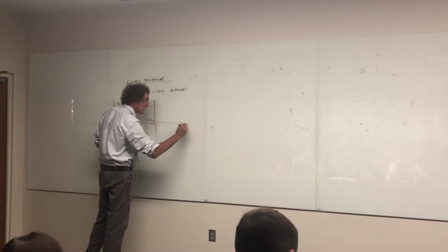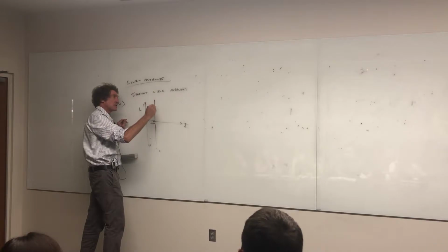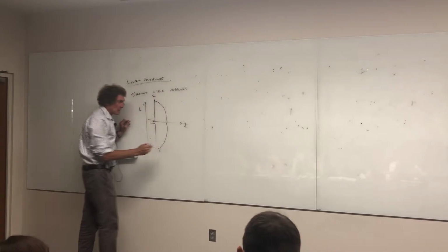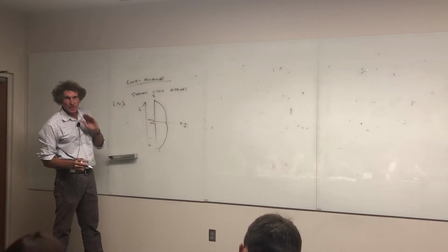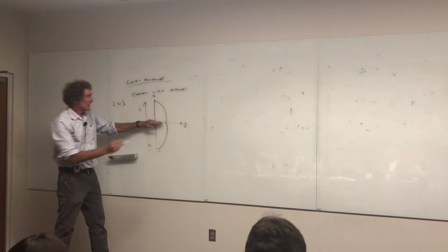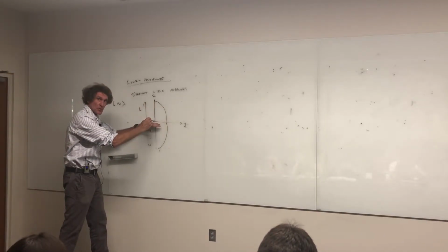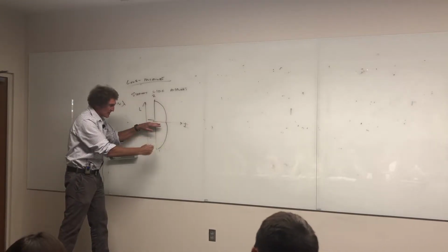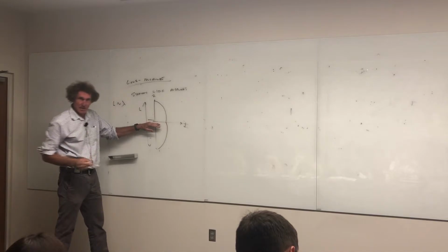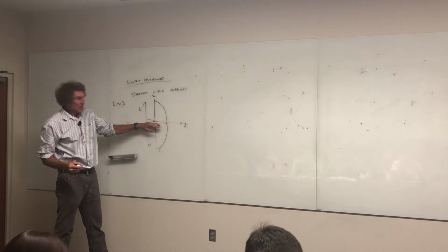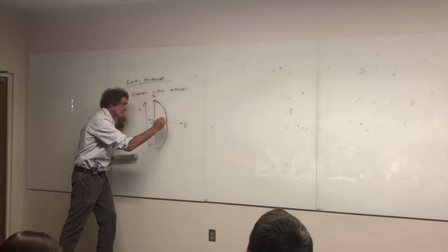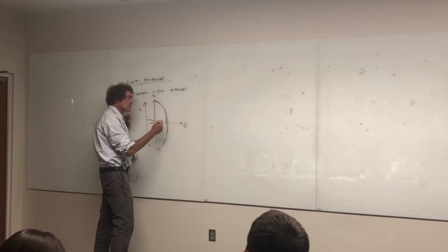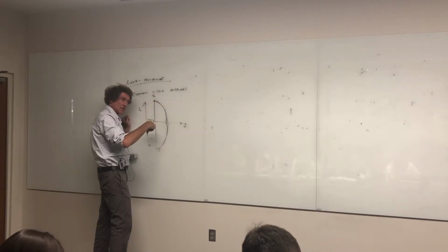And if we were to profile the current versus height, this is the z-axis, this is what you'll get. Now, depending on the actual length of the antenna and wavelengths, you could get this as an absolute null, where the current fed into that antenna would be theoretically zero. It's never theoretically zero. Where you could get this as a half wavelength and this as a half wavelength. That'd be a full wavelength antenna. We could also get something where it's a half wavelength, where this would be the current. So what I've done here is graph current versus position. Follow me? It's just the magnitude of current.